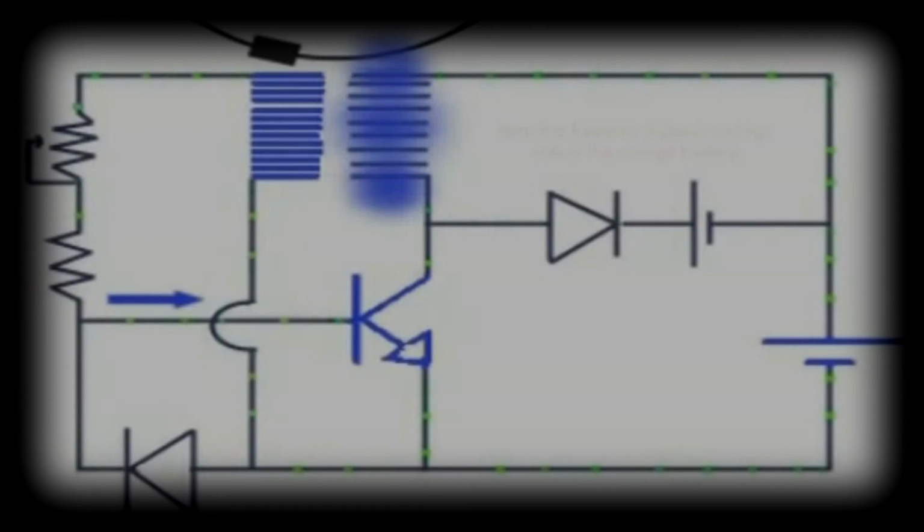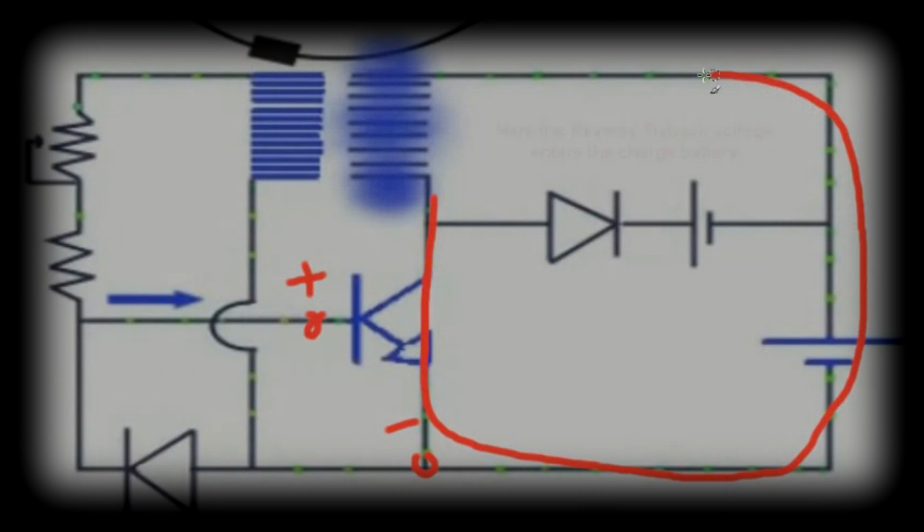And by that time, it passes by the trigger coil fully, initiating charge on the base of the transistor and the emitter with plus and minus charge on these 2 points to activate this transistor to close the gate. Basically, bring this arm down this point, closing the loop in this part of the circuit, establishing flow of charge from the source battery to the drive coil.